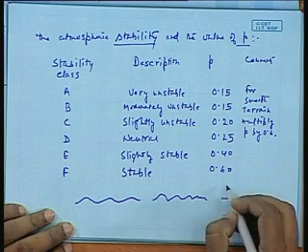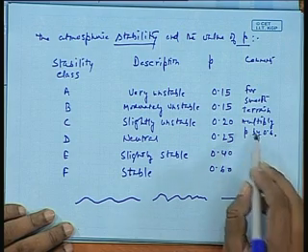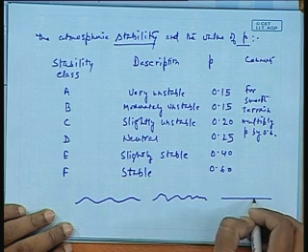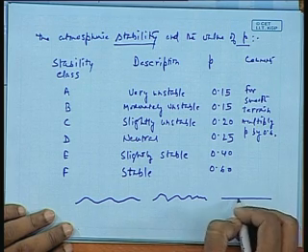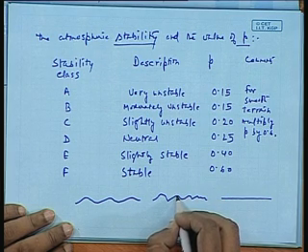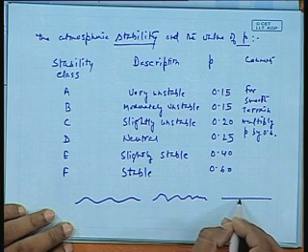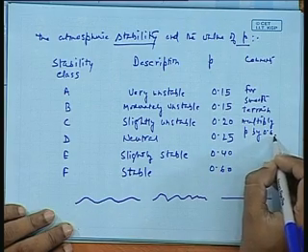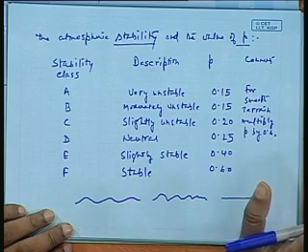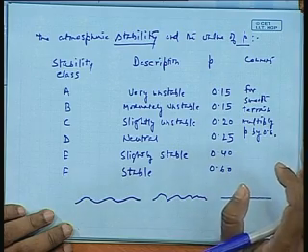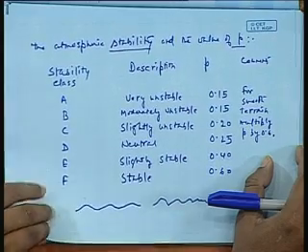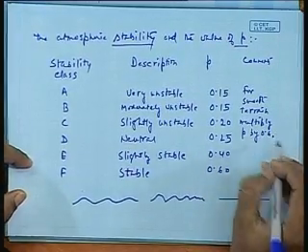So, if you are estimating the velocity at a surface like this and at a surface like this, at these two different surfaces, the value of P would be higher here than the value of P on the smooth terrain. And as you can see, multiplying P by 0.6 is essentially multiplying by a reducing factor. Okay. So, 0.6 becomes a reducing factor that we have come to know.